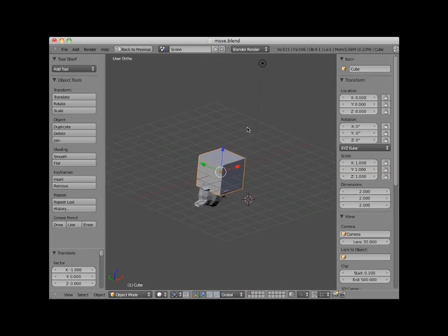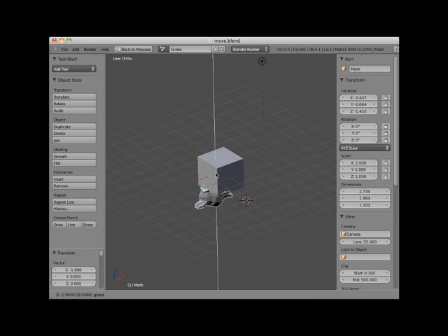Another very easy way to move an object, one that I use most frequently, is to use Blender's Translate widget. This is a tool located at the center of the object that contains red, blue, and green arrows. You can click on any of these arrows and move the object along the object's X, Y, or Z axis. Here I will select the monkey object and click and drag the blue arrow, moving it along the monkey's Z axis.